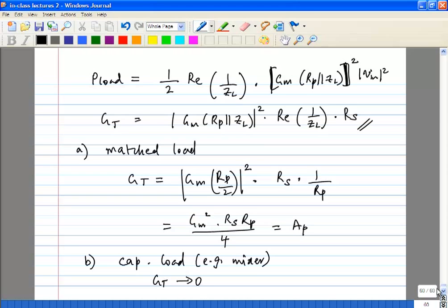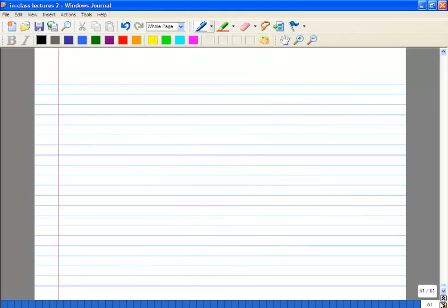Okay. Well and good. So now we have found out the gain, power gain, everything. Now you will notice that when we talked about the design of the LNA so far, we talked about input match, output match, stability, everything. We never talked about power consumption. Especially when we derived your minimum noise figure, we didn't put any bound on it. So if you try to achieve this minimum noise figure, you will find that the amount of power you will have to burn is huge, to hit this number.